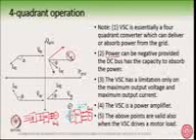But when the power is negative from the VSC and it flows into a capacitor, what will happen? The diode rectifier will not allow the power to flow back. It is a unidirectional device. Since this diode rectifier does not allow the power to flow, the voltage across this capacitor will go on rising, because the active power which is fed from the grid is now being stored in the capacitor in the form of half CV square. It will go on uncontrollably rising if you go on injecting power.